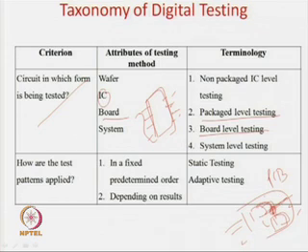If these chips are placed on a board and you are doing the testing, it is called board level testing. Now, many PCBs are connected and you have made a system like a PC or a laptop, and now you have to do the testing. It is more difficult, because in an IC you can get access to all the pins of the IC. Now, if I put it in a board, you can access only the pins which are the input and output of the PCB.